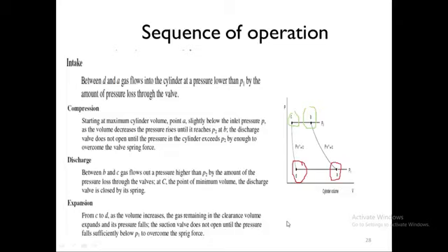So that's the entire process of a reciprocating compressor. I would like to show you a video also that will make it further clear to you, but I want you to pay attention to this clearance volume and the gas trapped in it, because that's what we will explain in volumetric efficiency, clearance volumetric efficiency. Okay, so let's look at the video.